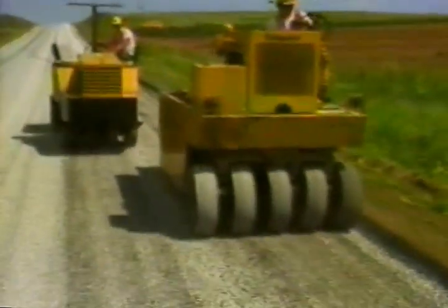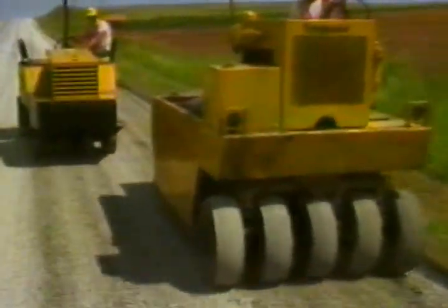Finally, tire contact with the freshly chipped surface must always be handled with care. Any twisting, spinning, or sliding of the tires will roll the chips over and expose the oil. Often, both the rock and the oil are removed, requiring difficult manual repairs.